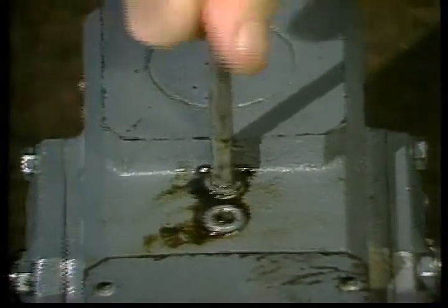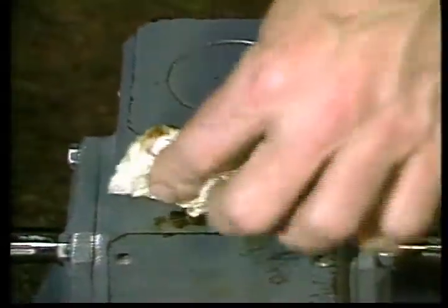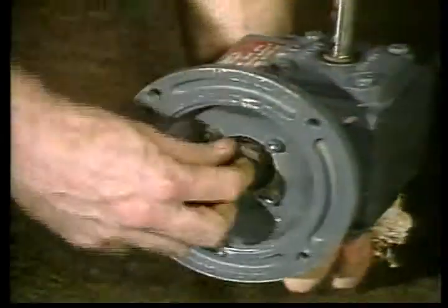If equipment will not be used for a long time or is being transported, make sure the bearings are thoroughly lubricated. To keep all parts well lubricated, it is good practice to rotate the equipment by hand occasionally.